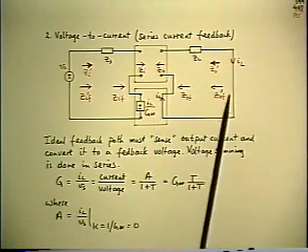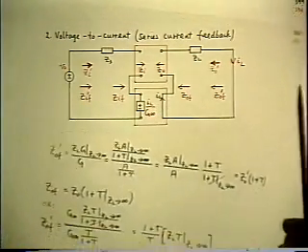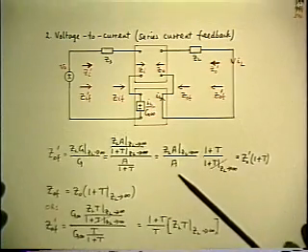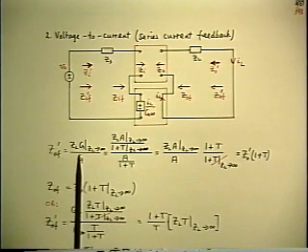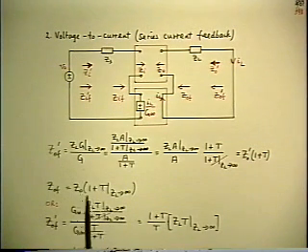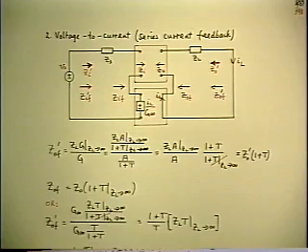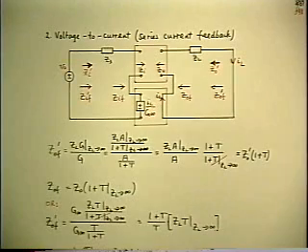So the only difference is the nature of the feedback connection at the output, and now you can use the input and output impedance theorems again to find what the effect of feedback is. We have a little problem at this point, though. The output impedance theorem was set up on the assumption that the output signal was a voltage. So actually you need a different form of the theorem if the output signal is a current. But I purposely set up these drawings so that we don't have to go back and rederive a new theorem. We can set it up by direct analogy with what we've done already.